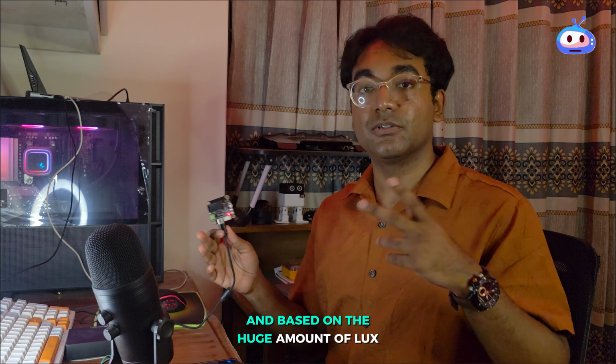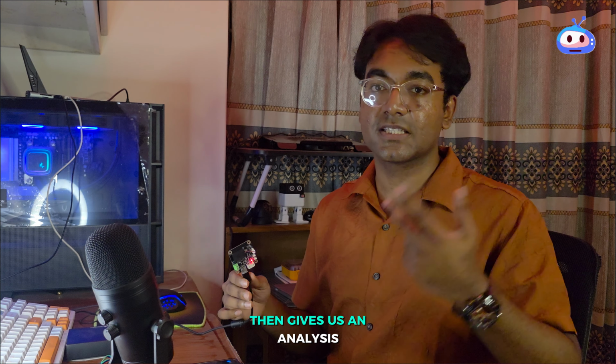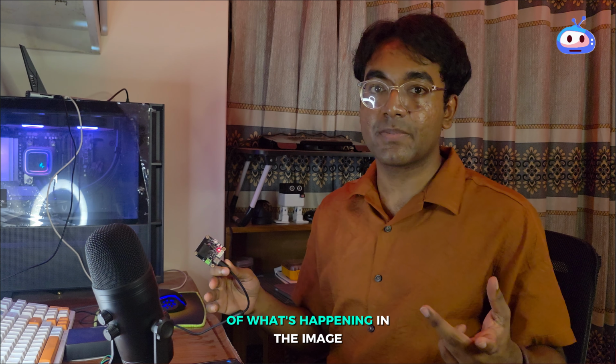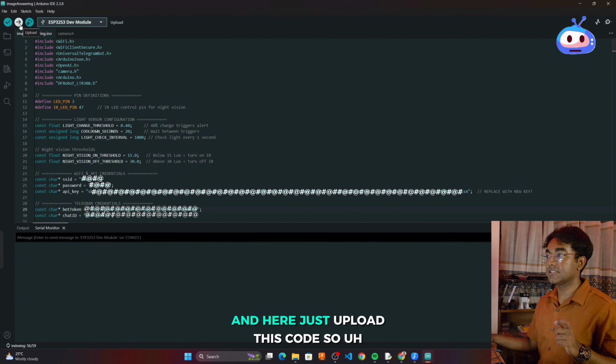It detects with the ambient light sensor the lux values, and based on a huge amount of lux change, around 40%, it captures an image, then sends it to the API of OpenAI, and then gives us an analysis of what's happening in the image. So it's just the most basic. So the same thing you have to do, just give your SSID, then password, then API key, bot token, and chat ID. And here just upload this code.